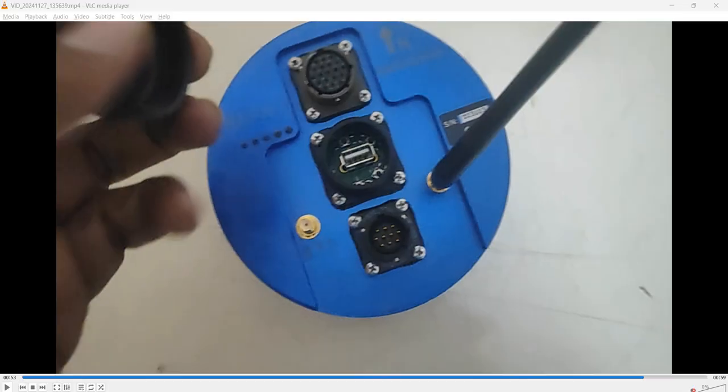As we are discussing the seismic recorder, seismometers give out electric signals, and to preserve these signals we need a device for permanently recording them. Since these seismometer output signals are generally very small, and they also contain noise, they have to be amplified and also filtered before recording. This is called analog signal preparation.